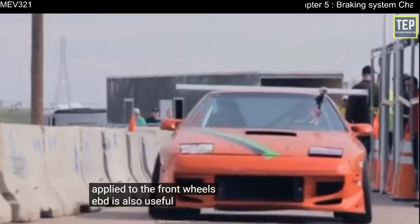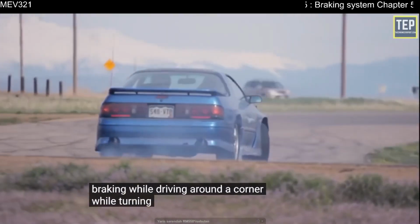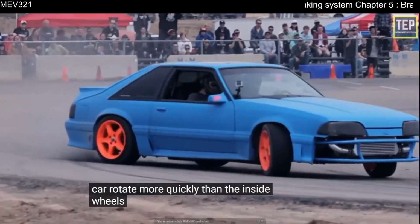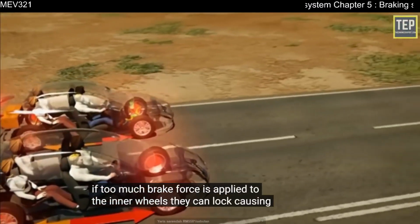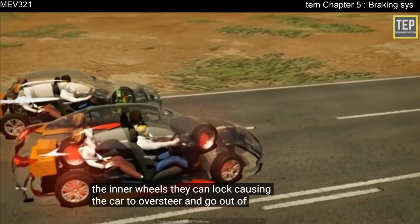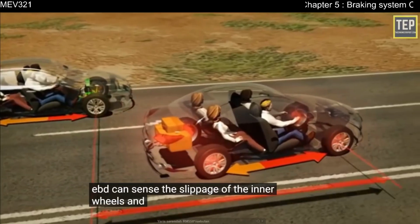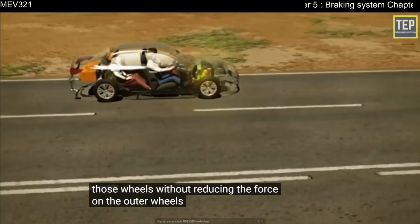EBD is also useful when the car is braking while driving around a corner. While turning, the outer wheels of the car rotate more quickly than the inside wheels. If too much brake force is applied to the inner wheels, they can lock, causing the car to oversteer and go out of control. EBD can sense the slippage of the inner wheels and reduce the brake force on those wheels, without reducing the force on the outer wheels.